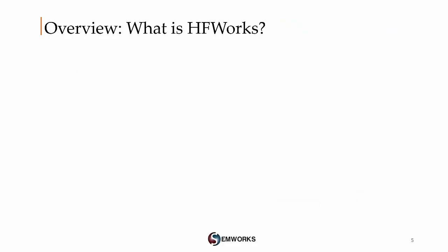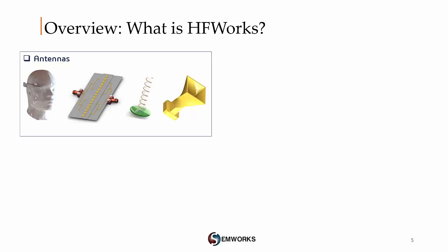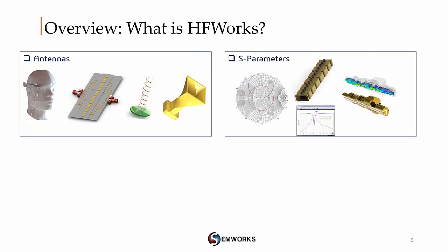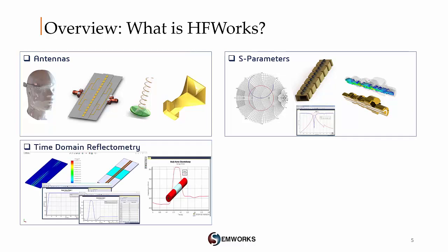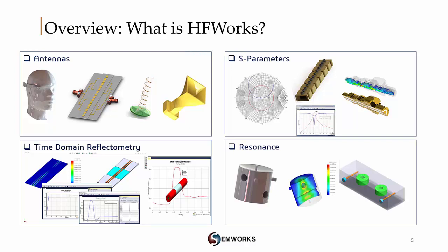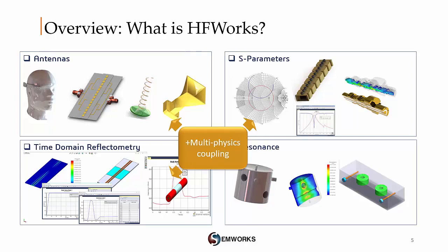HFWorks also covers a wide range of applications such as antennas of all types, like printed antennas, waveguides, wire antennas, horn antennas, etc. We also have the S-parameter solver for filters, oscillators, tuning elements, directional couplers, circulators, etc., the time domain reflectometry solver, and finally the resonance solver for dielectric resonators, etc. As we already mentioned, HFWorks comes with an integrated electrothermal analysis, providing a powerful and complete thermal analysis for electronic devices, ensuring their electrothermal reliability, which is available for antenna parameters and also TDR analysis.